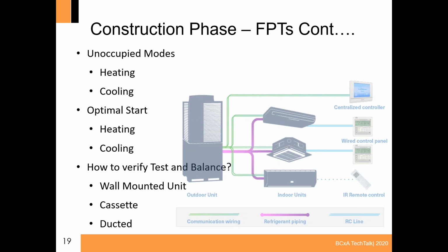And the last question, when would you suggest that a wind baffle be used on a VRF outdoor condensing unit? I believe those are used for low ambient conditions, if I remember correctly. I've never had to use them here just because our winters just don't get that cold, but I believe that's what they're used for.